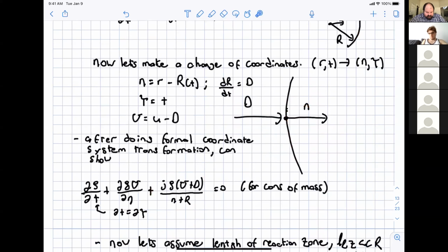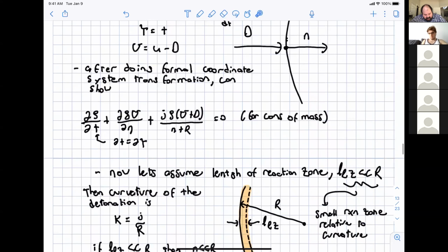What we wind up with for conservation of mass are fairly normal looking terms for the density and for the flow velocity relative to the detonation front. So basically, we're just looking at a stationary detonation, and then casting it into a 1D-like, or planar-like form.